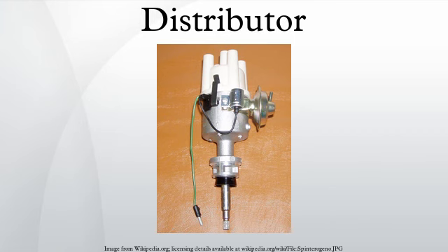The distributor cap is a prime example of a component that eventually succumbs to heat and vibration. It is a relatively easy and inexpensive part to replace if its Bakelite housing does not break or crack first. Carbon deposit accumulation or erosion of its metal terminals may also cause distributor cap failure.